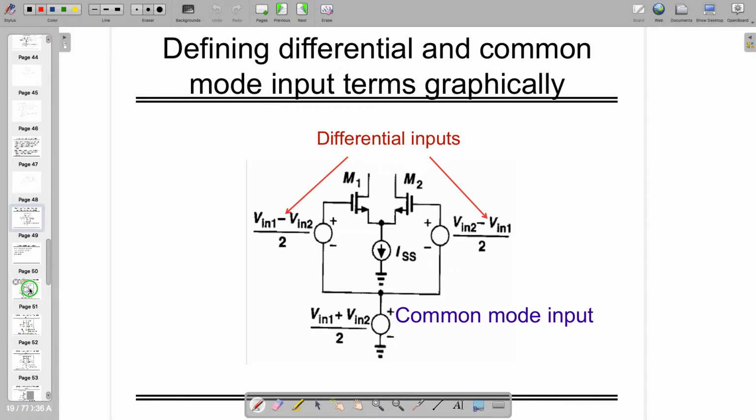Generally, this might be a DC quantity, but this is not compulsory, by the way. Sometimes we can use AC also, and AC can work as DC at a time. So in transient, each sample point is acting as a DC, and that's going to bias these transistors.